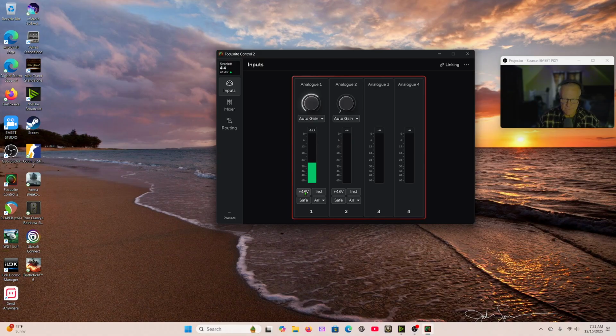And unless you're using a condenser mic, if you're using a dynamic mic like I'm using right now, a Fifine 688, it doesn't need power. It's USB or XLR, and the mic already has power. Dynamic mics don't usually need this. I don't know of any that do, really. But if you do have a condenser mic, most condenser mics need a 48-volt power supply in order to process the signal. So that will be lit if you are using a condenser mic.